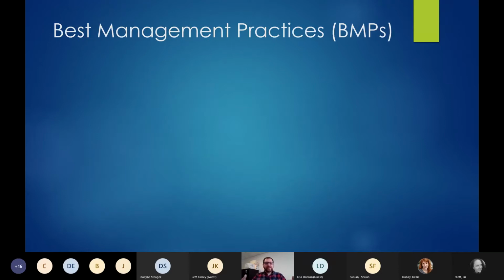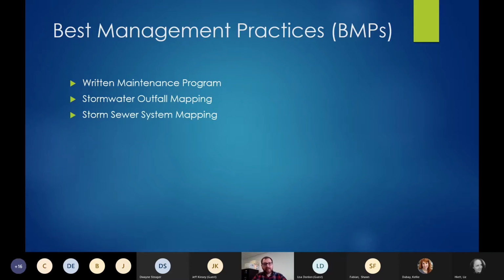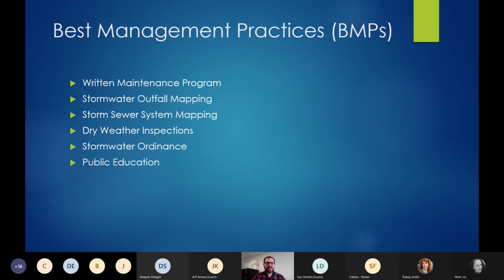All right, so DEP has provided 6 major best management practices, or BMPs, for townships or government agencies to follow. The first one is a written maintenance program. The second one is outfall mapping. The third is storm sewer system mapping, and those two are very closely related, and I'll talk a little bit about that in just a minute. The fourth is dry weather inspections. It's kind of the big part of this MCM. Fifth is stormwater ordinance, and then the sixth is public education.